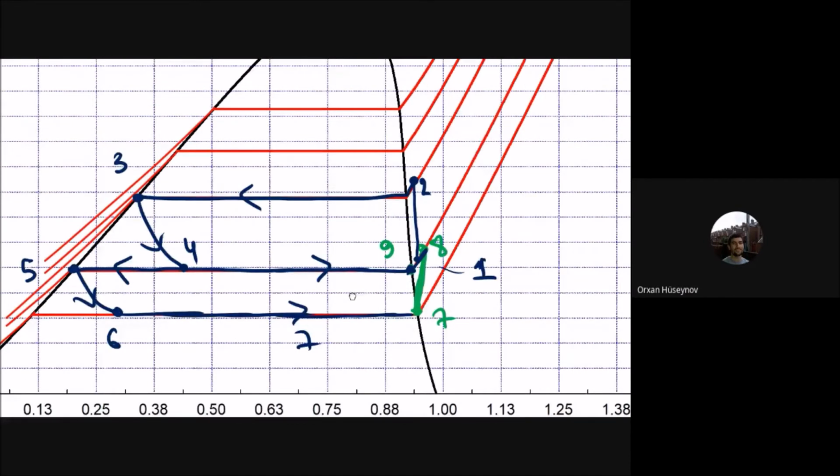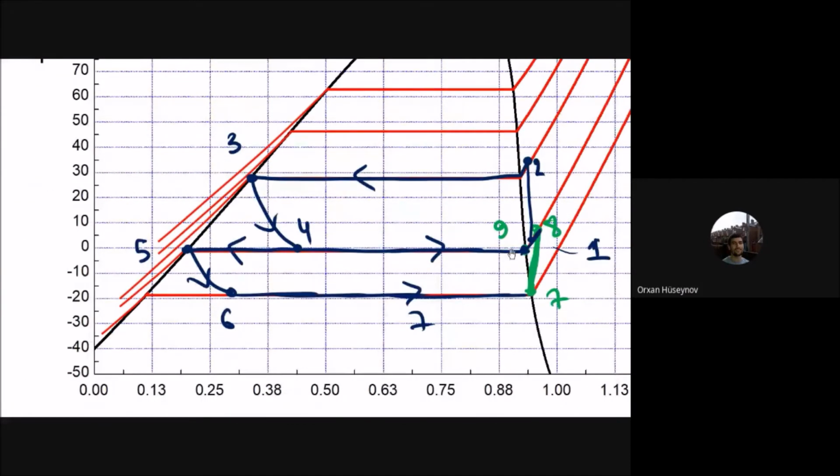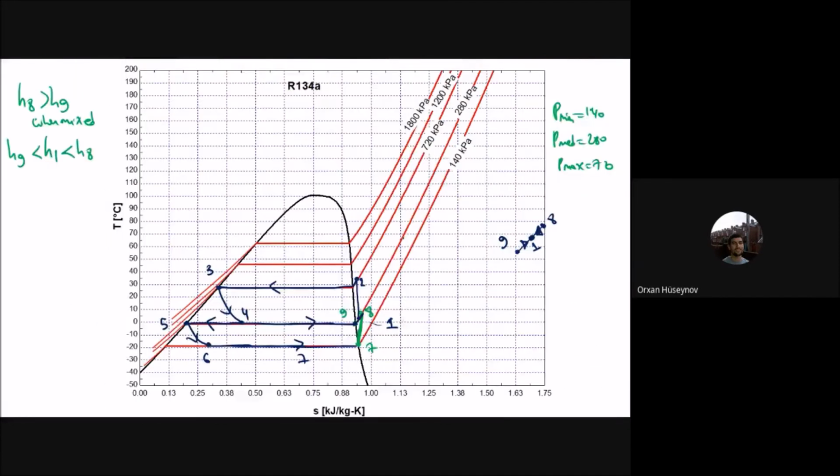As well as you have the QL effect here, because if you have not used the part here, then you have to drop the pressure from 3 to 6 prime here. You can see that part, and therefore you will have the drop in this QL, lower pressure, lower evaporator part. But since you are using 2 compressors, you have the additional heat cooling effect due to this area here. So let me just write it here. The first is the intercooling effect.